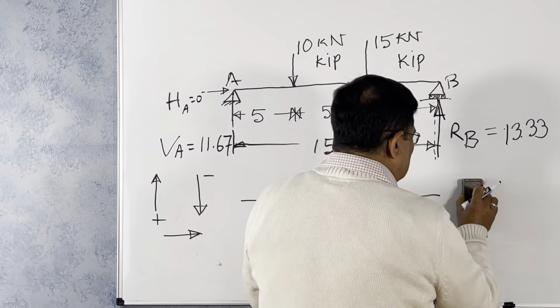Now see what the values are. This is the baseline. Now we have a convention for bending moment and shear force. This is positive. If you consider the right side and left side, if the moment is this way, or the moment at the other side is like this, it will form like a cup. It is forming like a cup. So this is a positive moment.